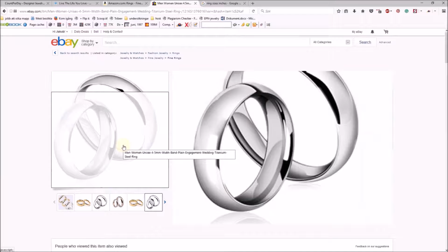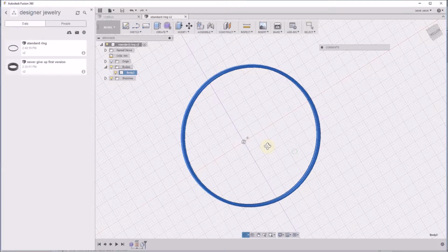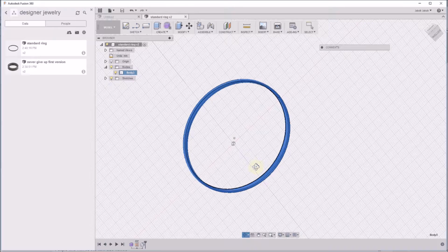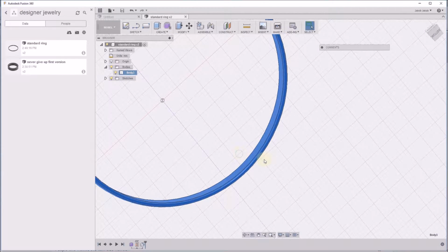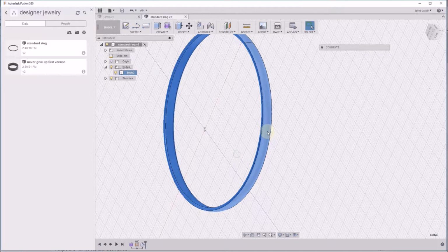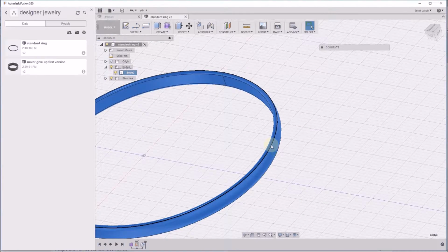We have the ring and it's somewhat thick in the middle and stretched, so I will show you one way of doing it. I'm doing it already here in Fusion 360. I have chosen to have this interface flat, and then I have twisted so I get this rounded, and then I add a fillet here.